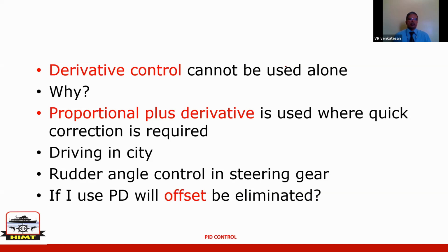So out of the three, proportional can be used alone. Commonly, it is used alone regularly. Integral can be used, but usually not done because its initial output is poor. Derivative can never be used alone. So you will see either P plus D or PID.